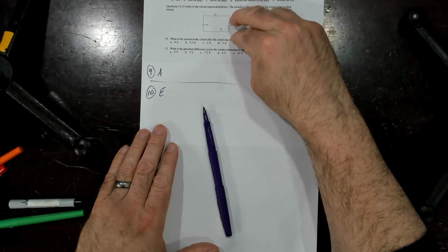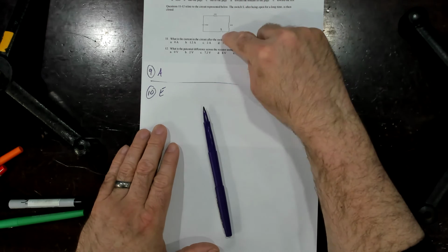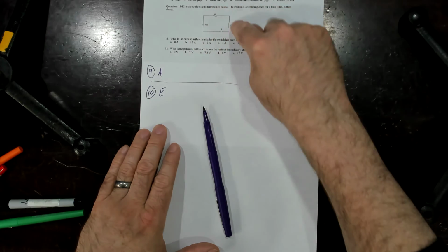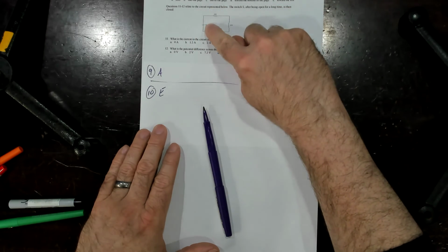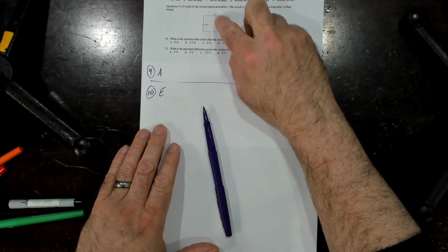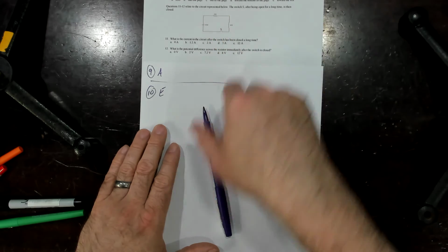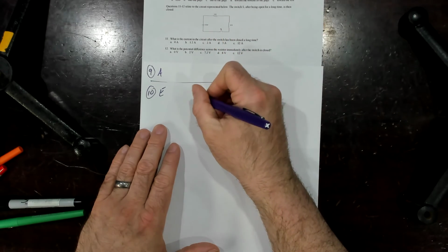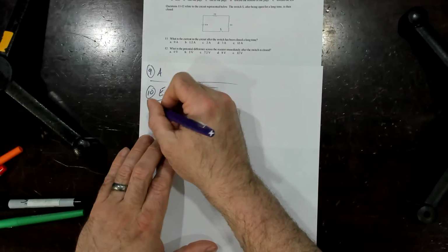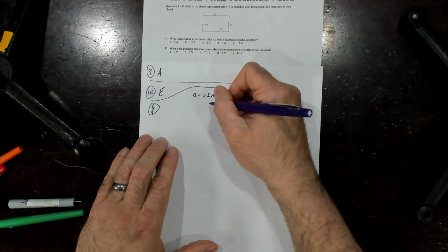It's going to have no induced voltage at all. And so basically it acts like a bare wire. After it's been closed for a long time, it's just the current running around. The inductor is doing nothing. So it's just 12 volts over 6 ohms. There's no delta V over the inductor once it's at full strength. And so you're like, oh, 12 volts over, I'll just use delta V as IR. Sorry, we're on to question 11 here. Delta V is IR, right? Trying to find the current.